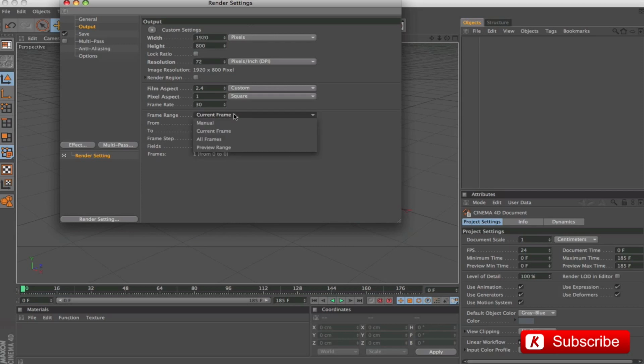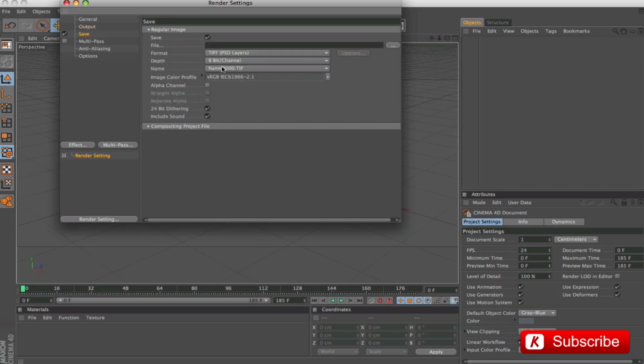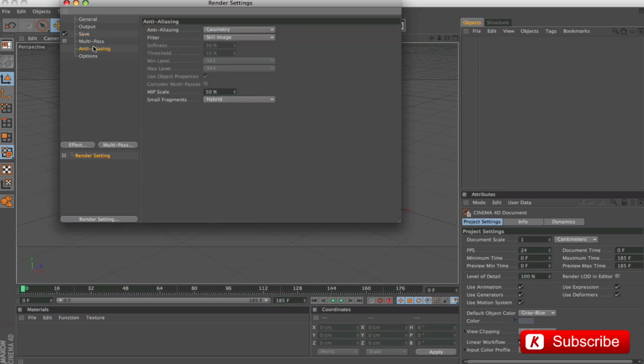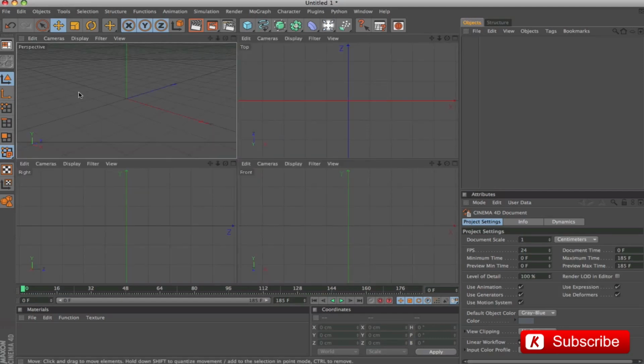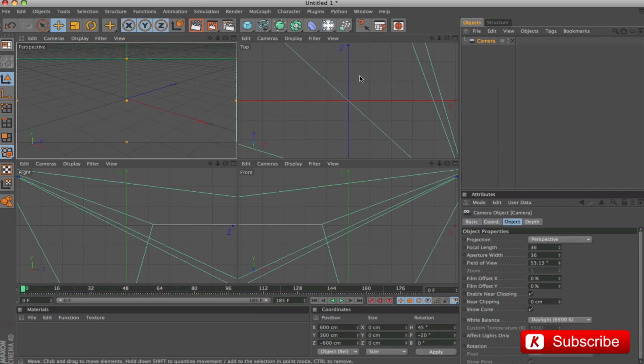We set all frames. Save as QuickTime Movie, and activate Alpha Channel. Anti-aliasing on best. Finally, insert a camera, and we set the Z coordinates, -1920.